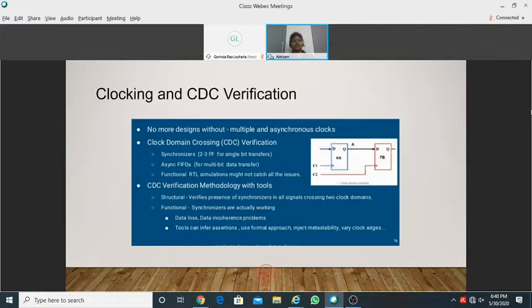Okay, and now, as I already described, clocking and CDC verification for multiple clock domain crossings have to be done. Basically, now we have synchronizers at each and every data path. So there will be a lot of clock domain crossings, and then you have those synchronizers being modeled with metastability injection, like a 2-cycle delay flip-flop can have a metastability. Because of metastability, it can land into a 3-cycle delay. So all these have to be correspondingly verified.